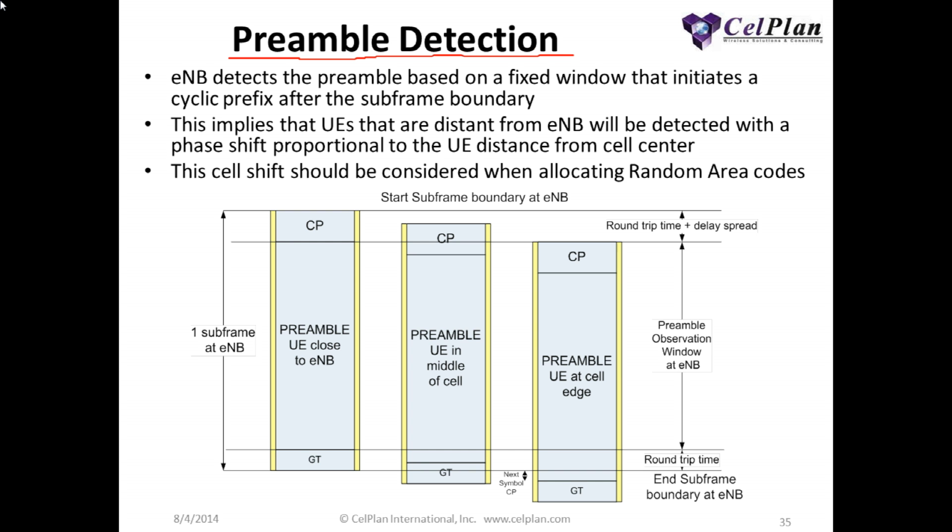In regular OFDM, to detect the regular channels and so on, we need to be very well synchronized to the start of the subframe. The reason for this is that we have to detect sines and cosines, and if we are not synchronized, the sine is not a sine anymore, it's a sine with a phase shift, so it cannot be properly extracted.